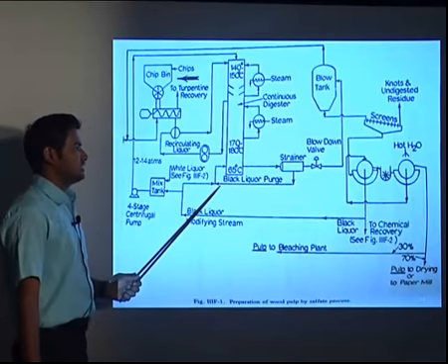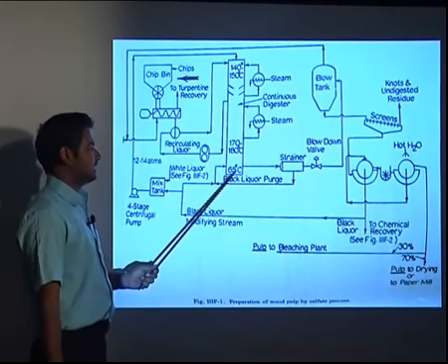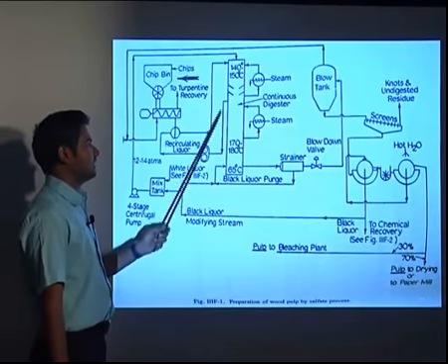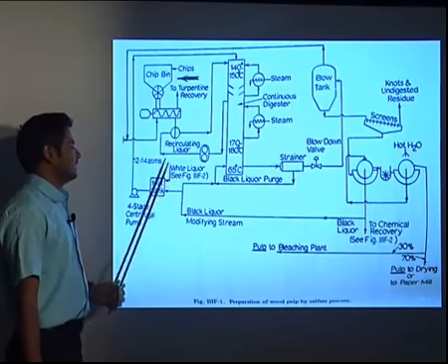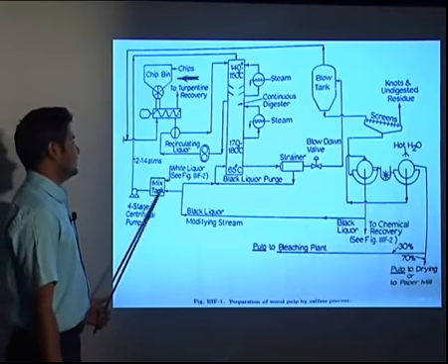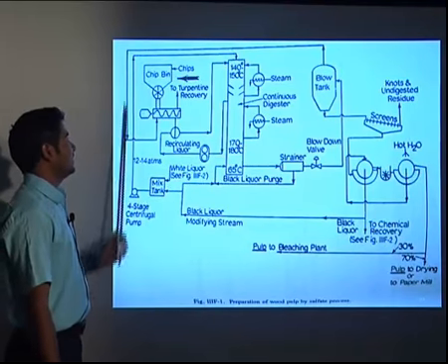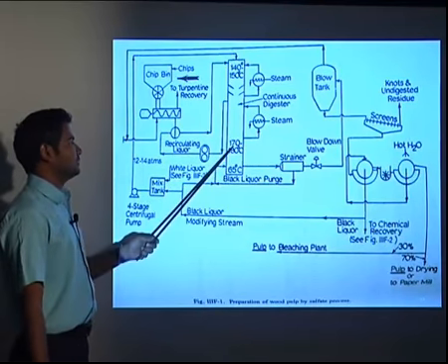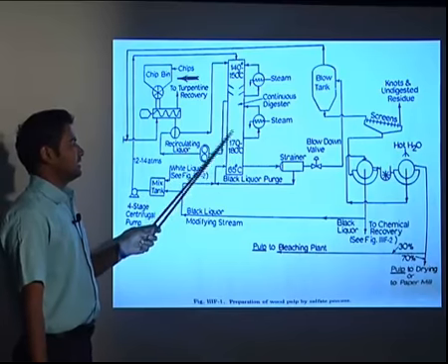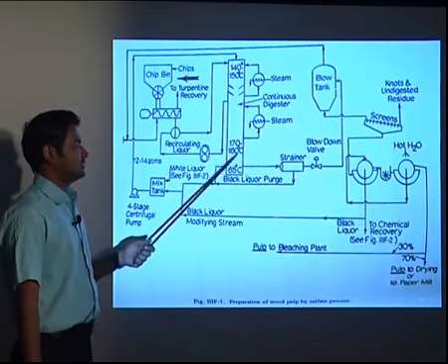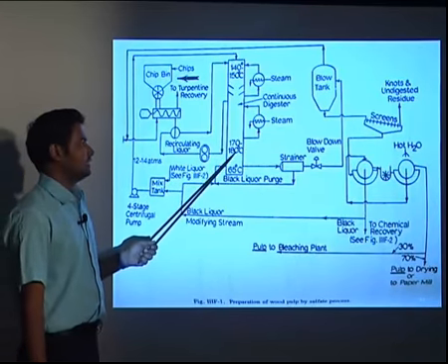Whereas the black liquor will be circulated here to maintain the temperature lower than the temperature of the digester. And in the mixture tank, whatever chemicals are used are recirculated in order to digest the material, so that the digestion mixture is effective.